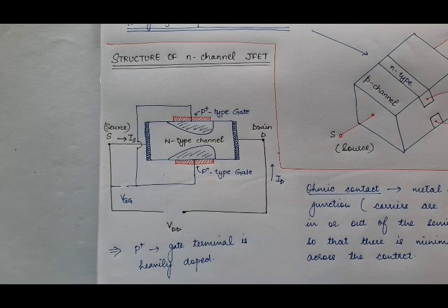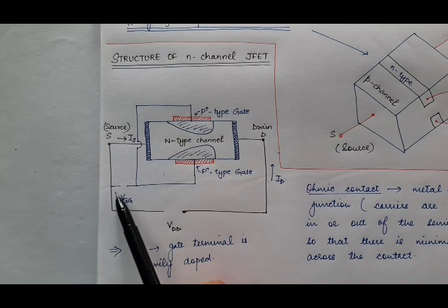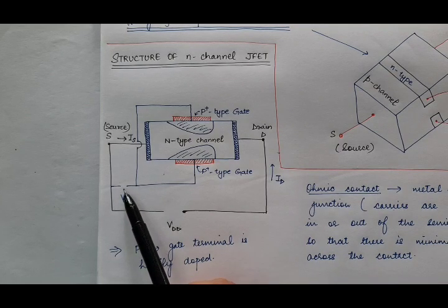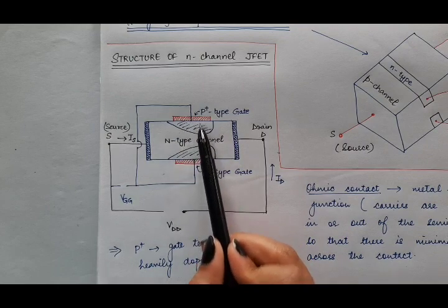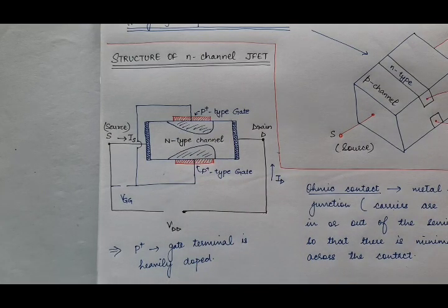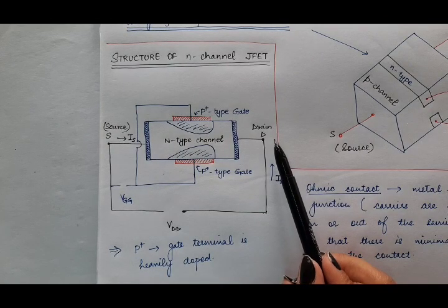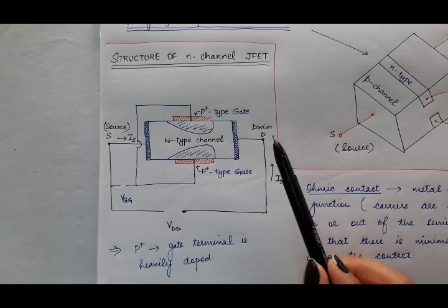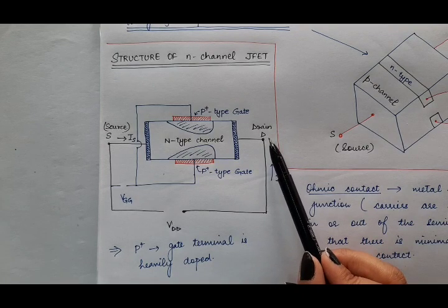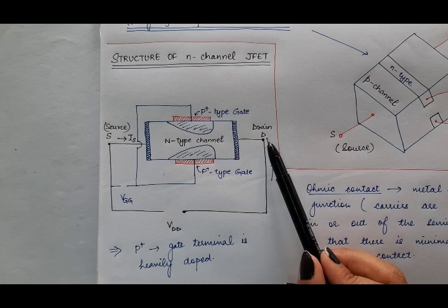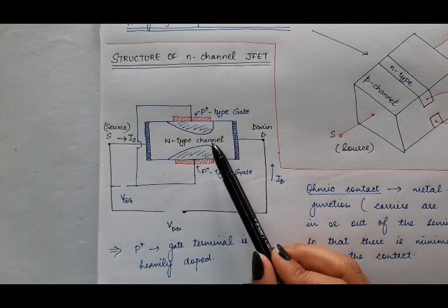But as soon as we apply external voltage here, the width of the depletion layer across these two PN junctions will change along the length of the bar. Why? We'll check it in our next article. So here just remember that the task of the drain is to collect or drain out the charge carriers, and it will only do so if it carries opposite potential to that of the channel.